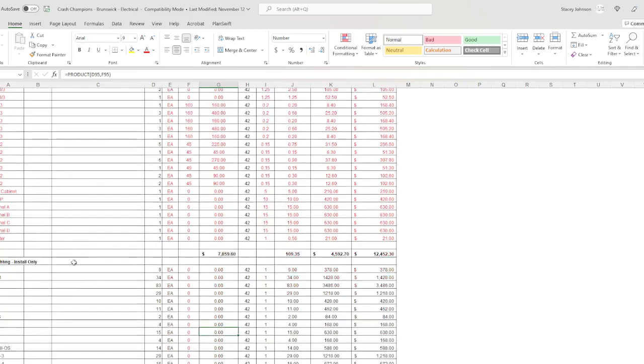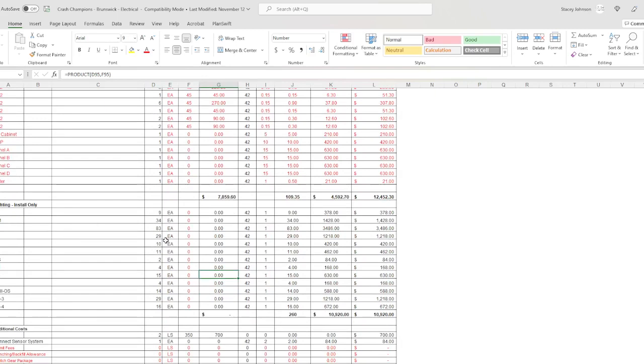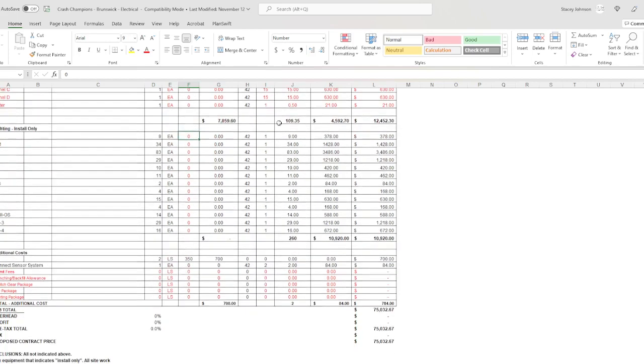All right. And then all of our lights, right? Counting tool, really good counting tool. And again, you're going to get your lighting package depending on the type of, if it's like an Applebee's or Cheesecake Factory, they have a supplier. You call them, they'll give you the material cost for all the lighting package, and you just fill in the blank afterwards. But of course, we give everything an hour for the lighting. And you can be even more detailed than that because most things don't take an hour. Unless it's a track light, then we give 0.25 of an hour for that.